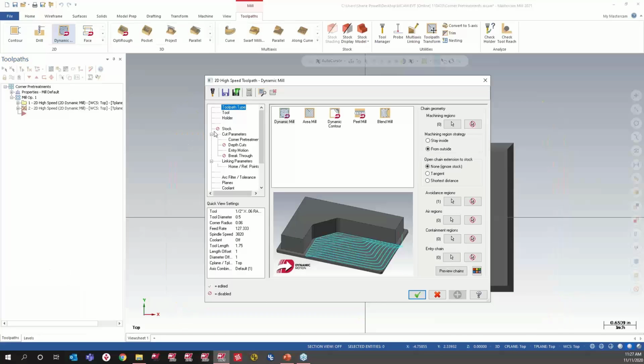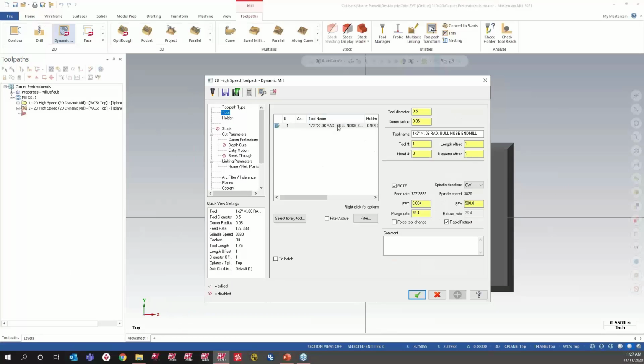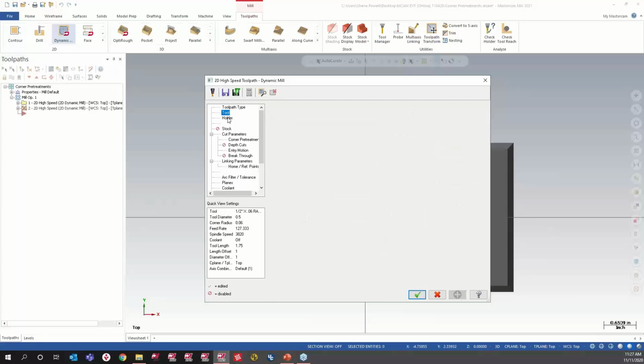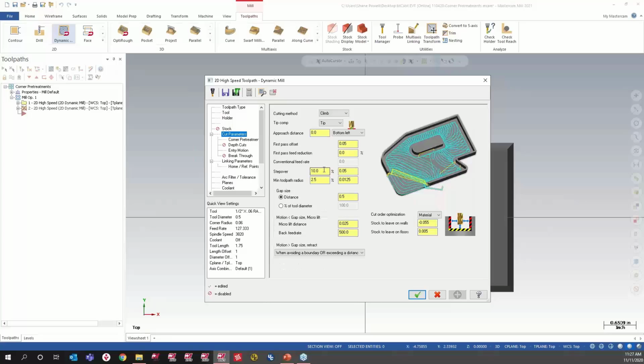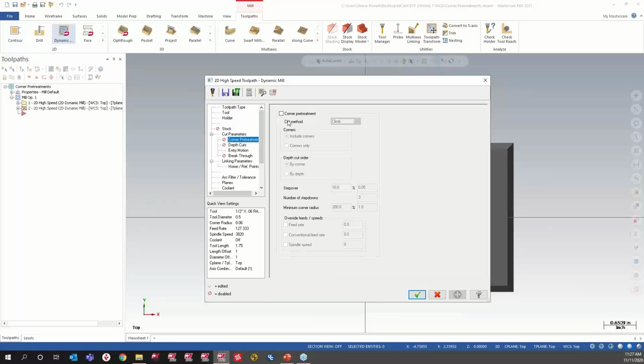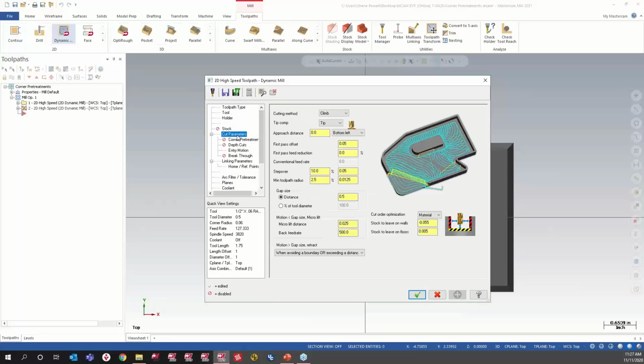Green check. I'm going to pick that tool, a 1/2 inch, 3 times diameter flute length, right? So it's 1.5 inches, and then to our washout 1 3/4 inches. And what I want to use is all of my flute length when I can after I've treated my corners. So for first, I just want to demonstrate what it does, you know, without using corner pretreatment.